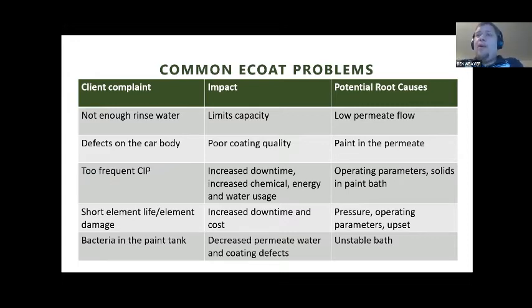Do we have the right operating parameters? Has there been an upset? One of the most common upsets we see in the industry is, either on startup or after a clean in place, a pressure surge or water hammer that can cause a seal breach or an element defect.